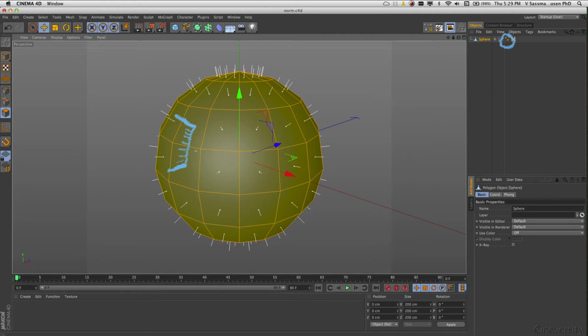And we don't want to have that, of course, always smooth. When we have, for example, a cube, then we want to have a sharp edge, for example, or something like that, a bevel. And then we want to have something that has a definition of these edges. Either way, not smooth and round. And so we can say the angle here from this polygon to this polygon, or from this normal to this normal, shouldn't have a greater value than whatever we put into the Phong. And there's of course another option that we say this edge is Phong broken, and then it will not be smoothed along when we say so.